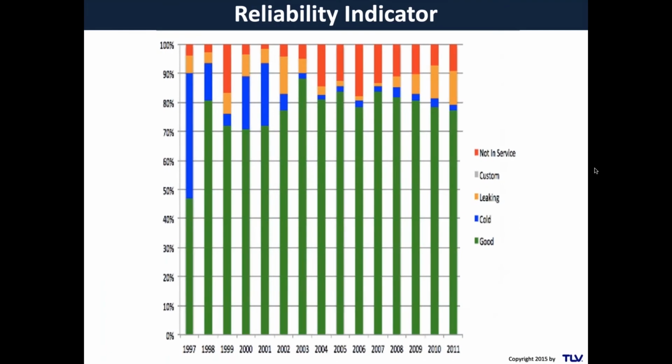We like to see the reliability indicator where a site has had a sustainable steam trap management program every year. They're maintaining a high percentage of good traps. Above 75% good is kind of a benchmark. If you maintain above that, you should see less reliability issues.